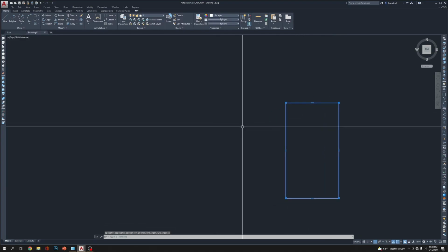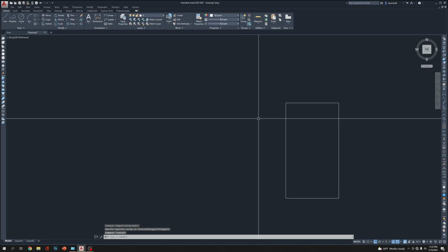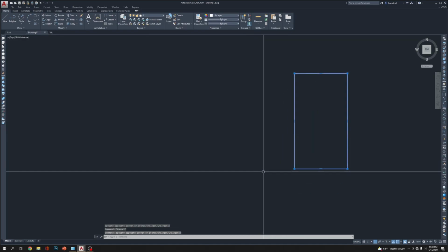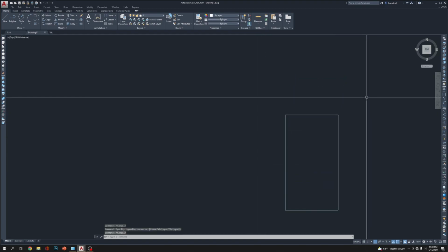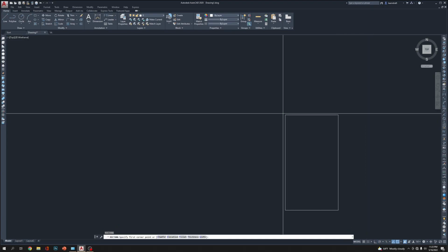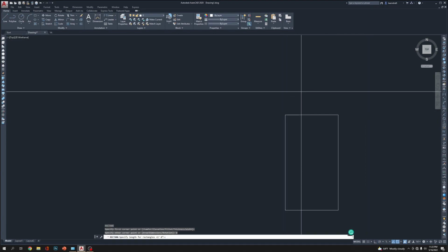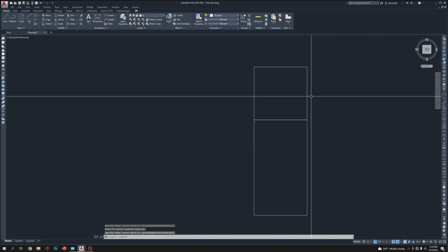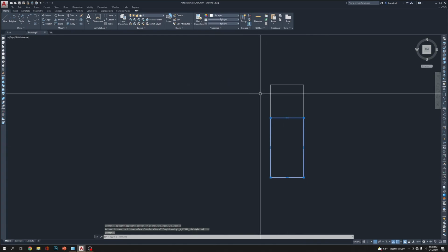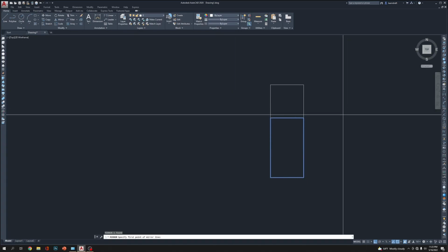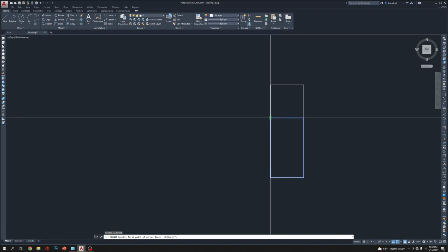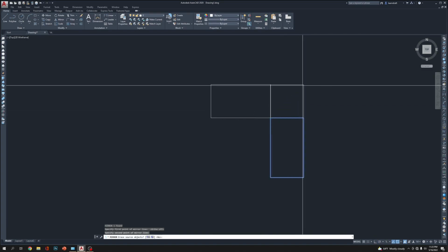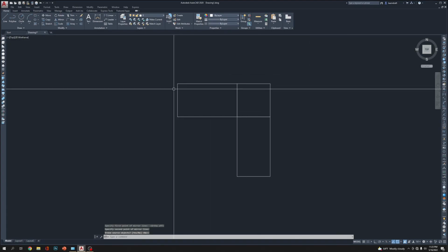And I'm going to copy this one now. No, yes, let's copy it. Actually, I don't want to copy it right away. Why not? Because I want to make a corner first. So I'm going to create another rectangle, D, enter. It's going to be 20, enter, 20, enter, click, and then enter. Okay, so I want this one to go here. I'm going to mirror it, turning off F8, click here, click there, and enter. So it becomes a corner, right?